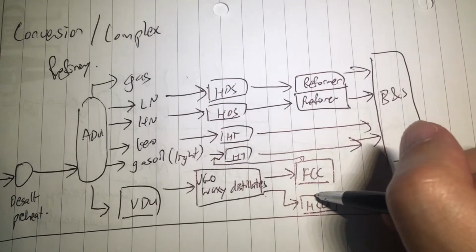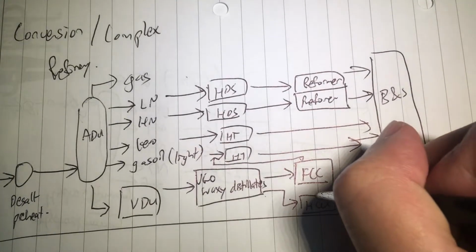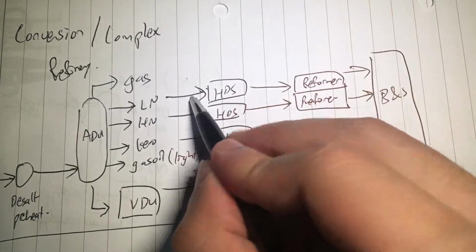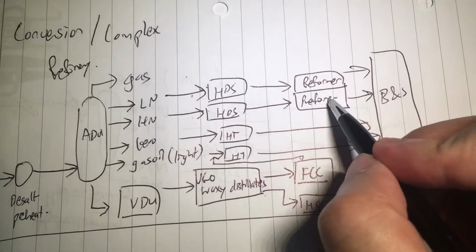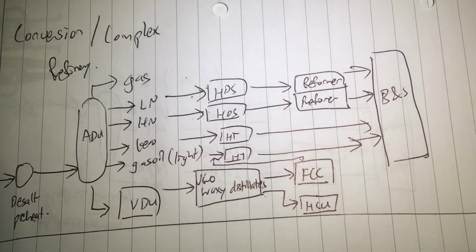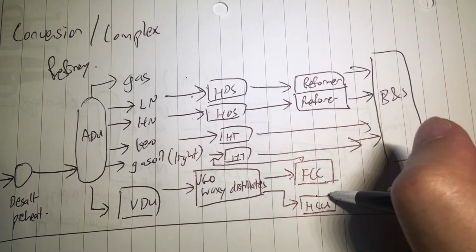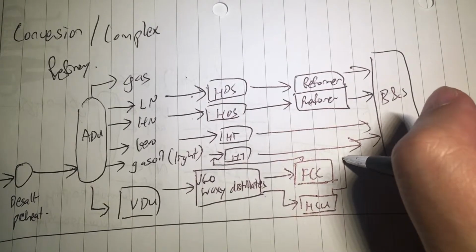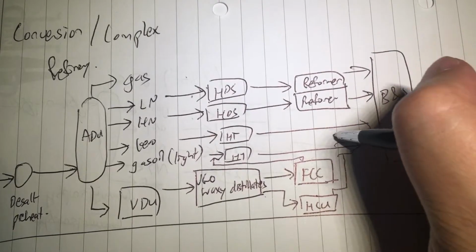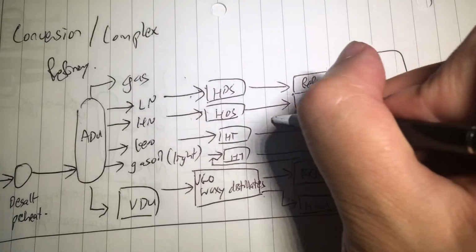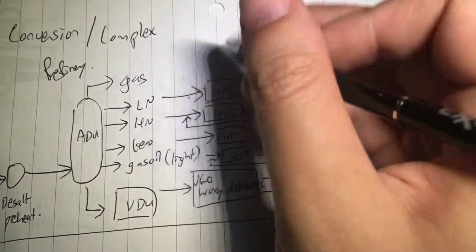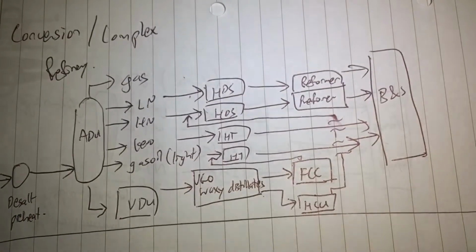Okay, so the naphtha from the hydrocracker, I need to send it to the hydrodesulfurizer before reforming because there may be still some mercaptans inside. Nonetheless, it is much lower than what is normally inside the naphtha from the crude distillation unit.